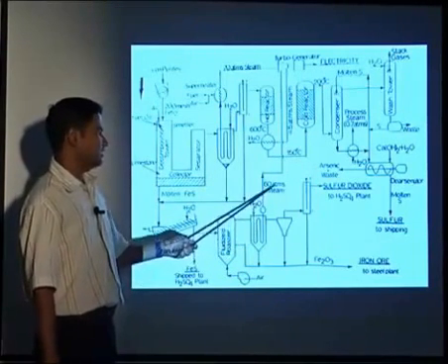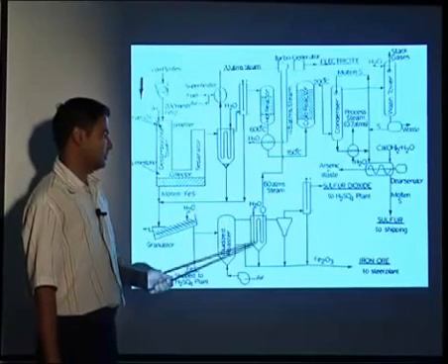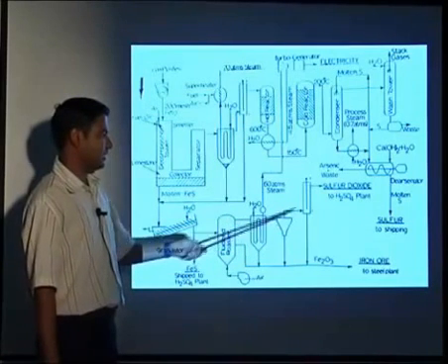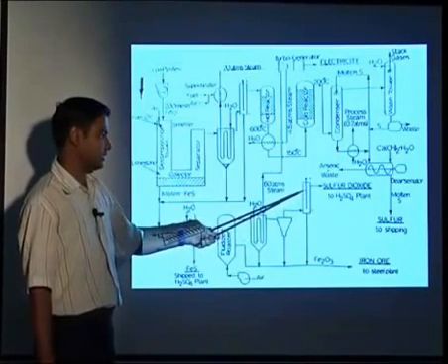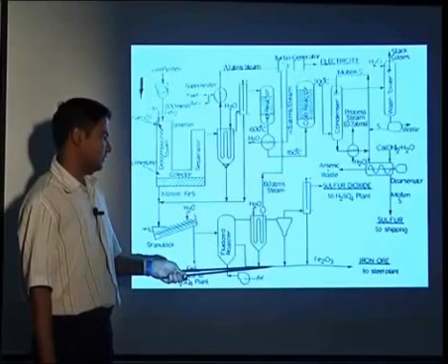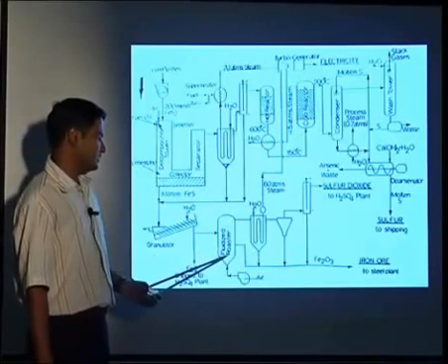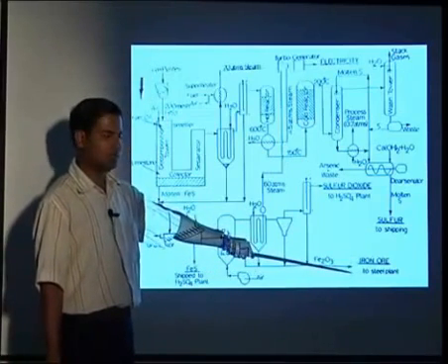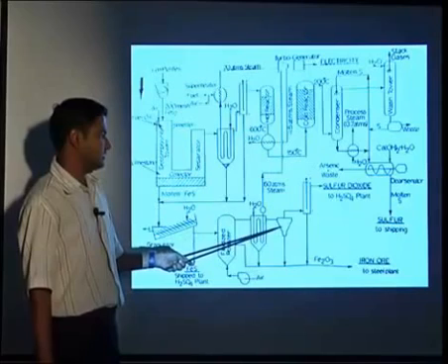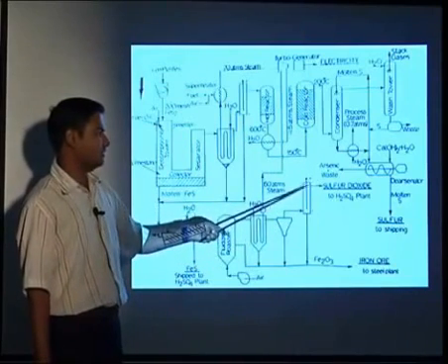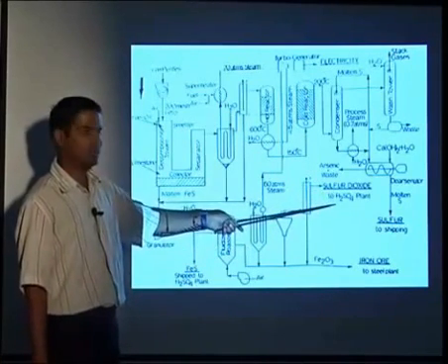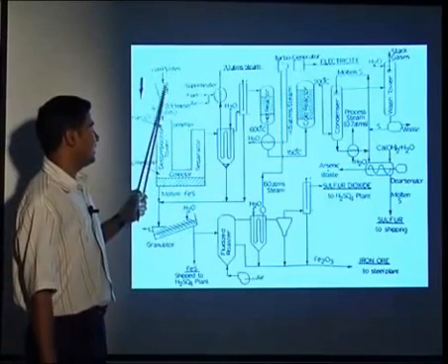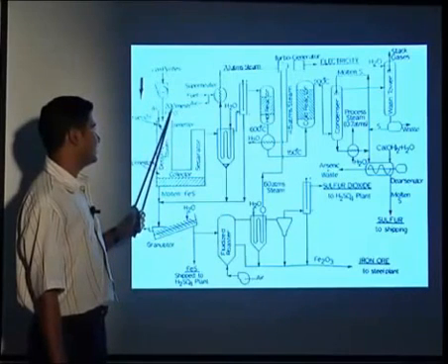Then water is used to cool, and we get over here 60 atmosphere steam because of the heat evolution. Then we are cleaning the gases in the cyclone separator and the electrostatic precipitator. Whatever Fe2O3 we are getting, which is formed in the fluidized roaster, we are sending to the iron ore, or that is used in steel plants. And the gases, that is SO2, which we are getting after the precipitator, we are sending to the sulfuric acid plant.